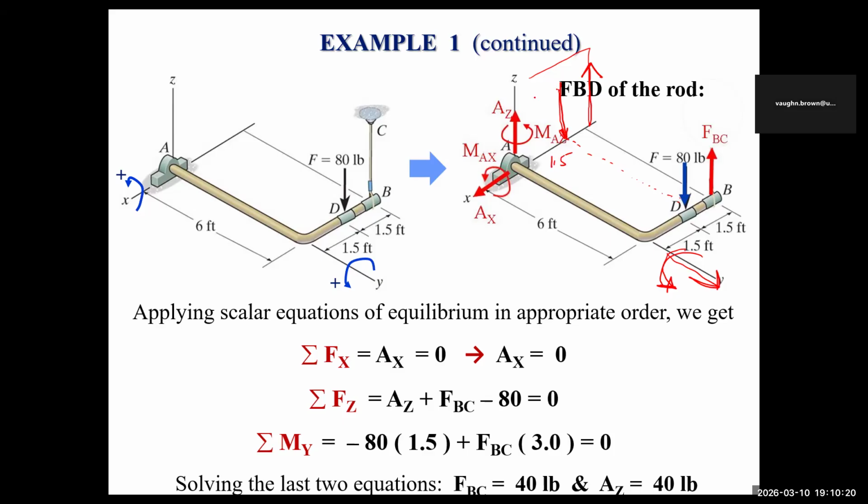So you have what? You have a perpendicular distance. So you have a force and your perpendicular distance. So you see it is 1.5 times the force, and it's going down in that direction down there. Where is it going to turn it around the y? Remember the y, so this way is positive. If it's going to turn it in the opposite direction, remember this is the axis, the turning axis.